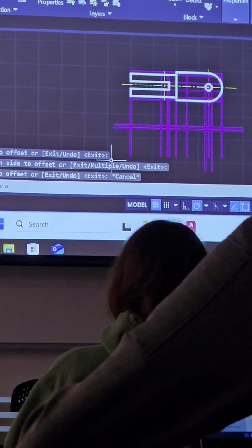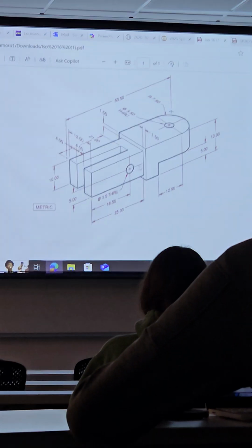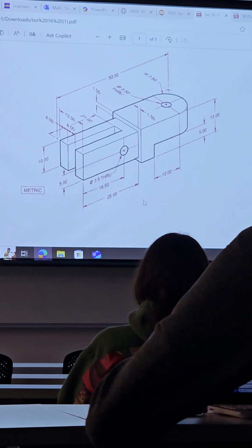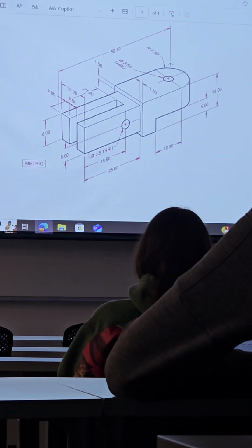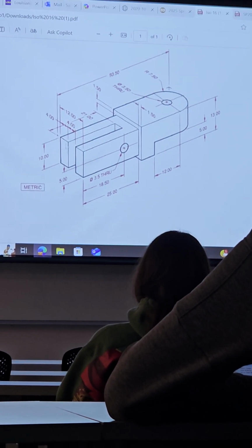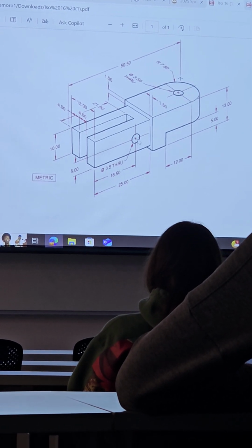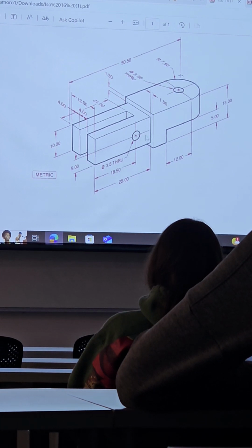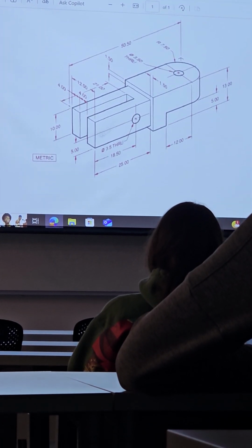All right. The next one I'm interested in is the distance to the center of this hole, and that is indicated as being 5 units from the bottom edge. You see this dimension here? Well, this whole fork is only 10 units high, so that tells me that the center of this hole is in the center of this object. So they could have reflected this with a center line right here instead of an extension.